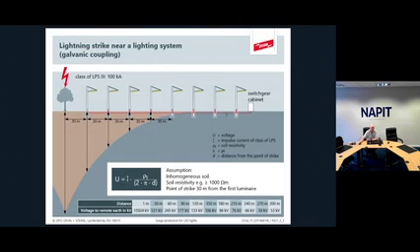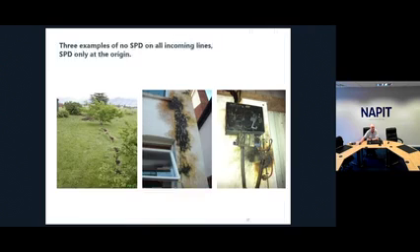So as I was saying earlier, there's a massive rise in ground potential when lightning hits, say, a tree. So in this graphic, using the resistivity of the soil, at the point of impact, we've got 15 MV. And after a couple of 100 meters, we're looking at 76 kV. So over quite a big distance, you're looking at some pretty substantial induced currents down any buried cables in the vicinity of a lightning strike. And this is why you can't just think about the origin where the meter is. Are there any other cables buried in the ground which could bring a surge back into that building?